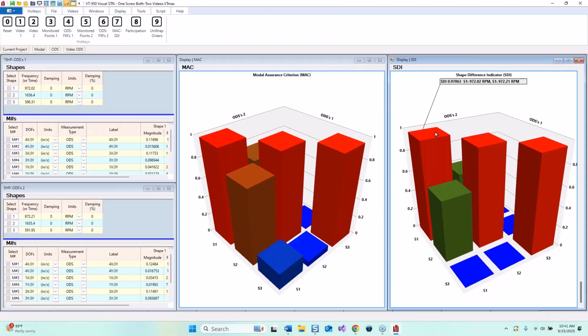We could do the same thing. We could actually curve fit, and we did this last month in the webinar. We curve fit some ODS FRFs and got what we call OMA, or operating modal analysis mode shapes. So again, you're capturing the response, but if you don't measure the force, then you need to measure these ODS FRFs or a cross spectrum. You can take a reference and calculate a cross spectrum, which most analyzers can compute, and we also can compute that in MEscope.